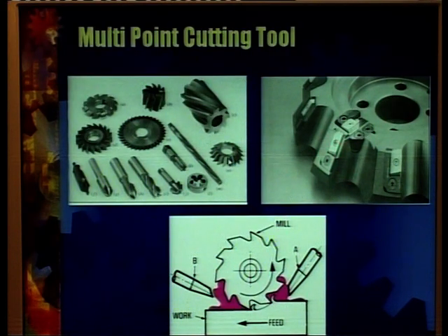The only difference between this cutter and this cutter is that in this cutter the edges have been ground onto the same shaft. From the same piece the teeth have been ground, and after use, if these teeth get blunt, then they have to be reground, and once the regrounding limit has been exceeded, then the whole tool, or the whole cutter, needs to be replaced.